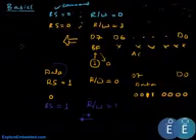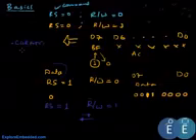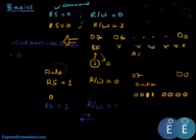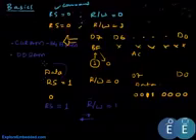The one point to emphasize here is the CG-RAM, it stores the custom characters. You can rewrite it, it is of 64 bytes, and you can store 8 characters. Now the DD-RAM is the display data RAM, or the RAM which is used by the graphics controller to display characters on the LCD. So this is about the basics.